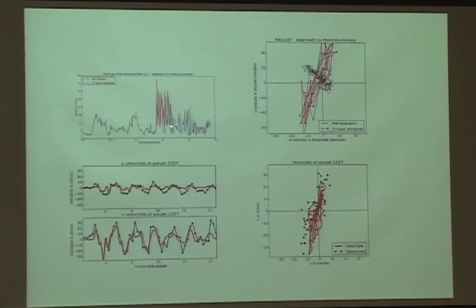And the black line here is the actual observation, the magnitude of the speed. The part that's highlighted in red is just a 5-hour window around when the tsunami actually arrived. And this is the same data, but plotted in the UV plane. So in the horizontal, well, east-west and north-south components of velocity at this particular point. And what's interesting here is that the black part, the original sort of tidal currents going in and out of the harbor, are moving in one direction, but the tsunami current that came in is moving almost orthogonal to that and has much larger amplitude as well.